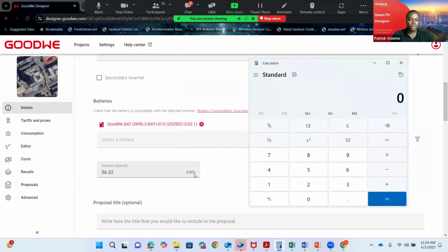And for each inverter, if you do a maximum of 6, then 6.3 times 6, and then times 10, gives you around 3.3 megawatt hour of storage if you're doing the maximum: 500 kilowatts, 3.3 megawatt hour.